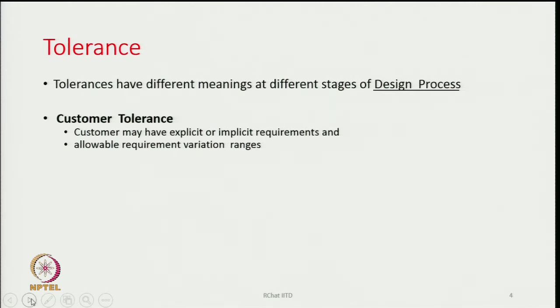If I say I want to buy 10 tons of cotton yarn from a particular factory, and we specify that the cotton yarn count should be 20s NE, they can give a tolerance of 20s NE plus minus 1 NE. So, as long as any test that we perform gives a value varying between 19 to 21, it will be acceptable to me.